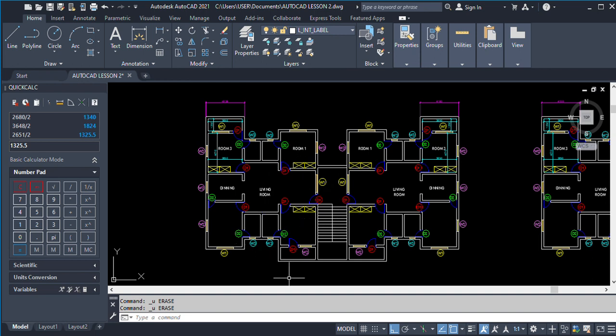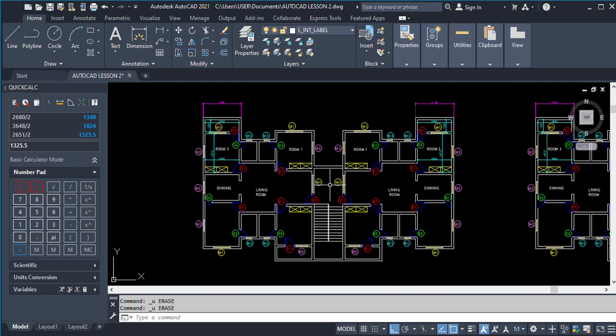We talk about paneling and why we do it like that, why we insert columns where we insert them, why we insert beams where we insert them. But if there is no time, we just prepare the panel and then move straight to Prokon Structure to do the analysis. And mind you, before you use software to do analysis, you must know the manual calculation of it, because the software may not make the mistake, it's you, because what you give in is what the software is going to give out. It's garbage in, garbage out.